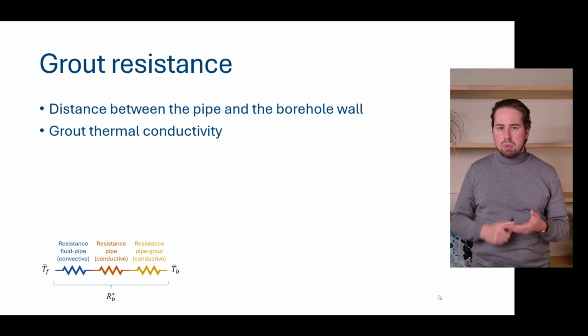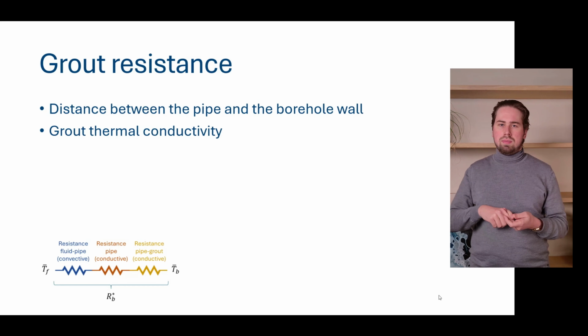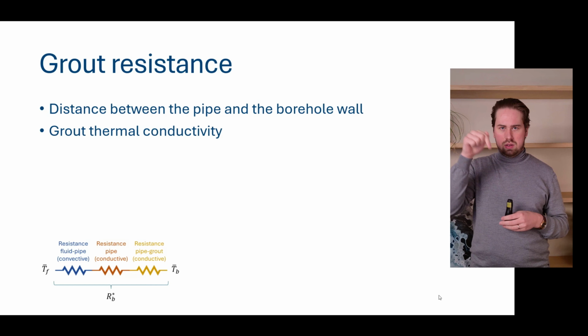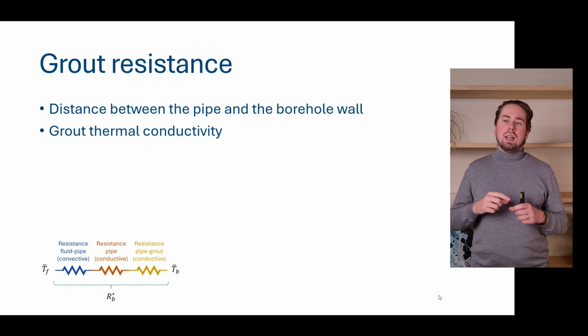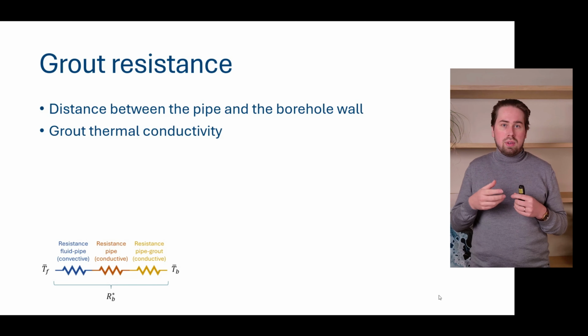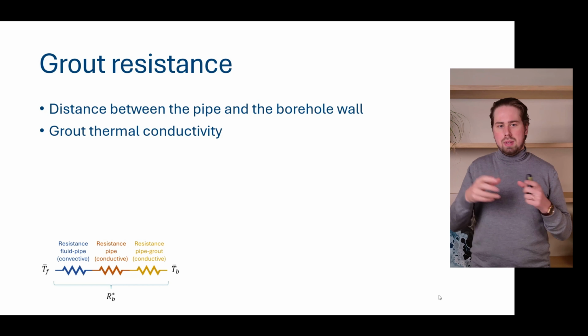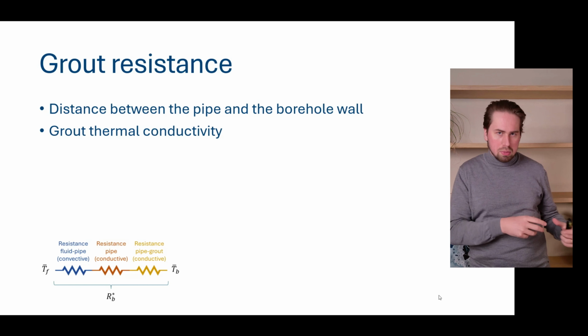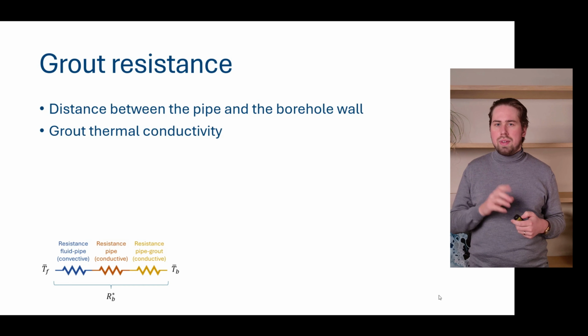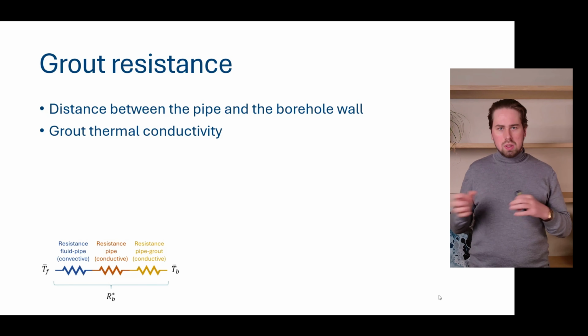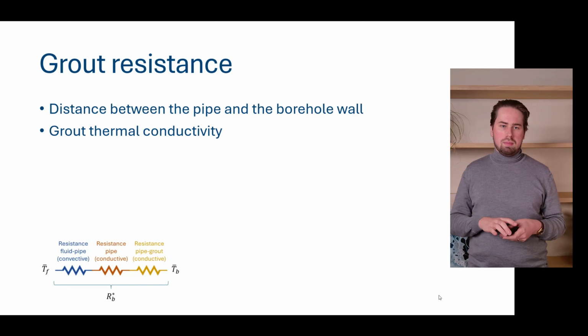Now there is another important element related to the grout. You can't enhance it forever, because in the end you need to get it down into your borehole. Therefore you need to have pumpability of your fluids, the ability of your material, your grout, to be pumped down there. So always contact your driller to see what is feasible there.